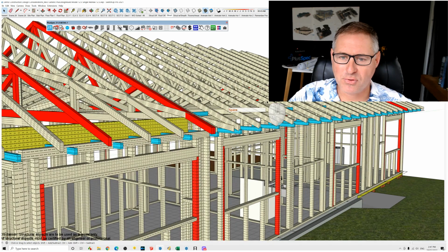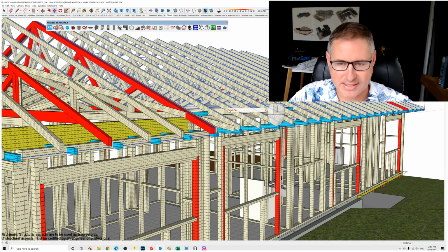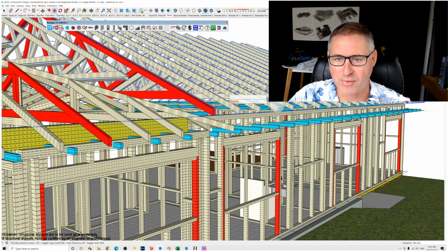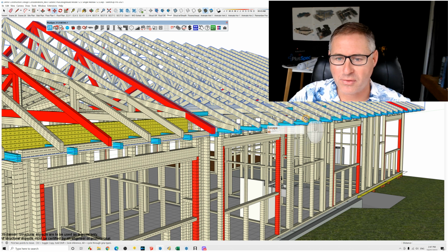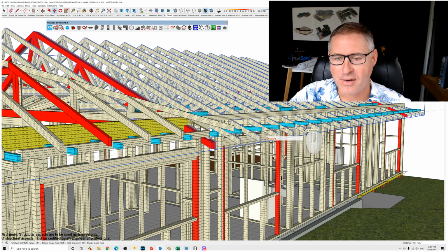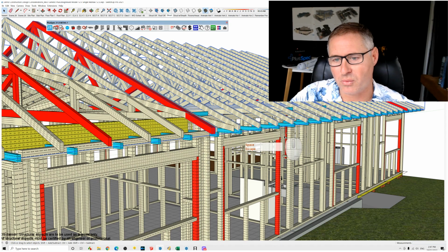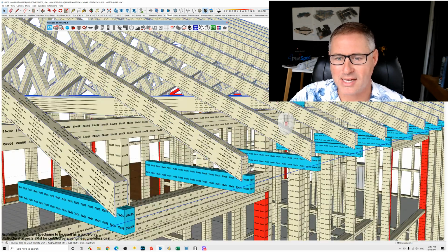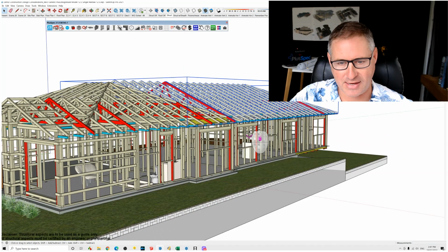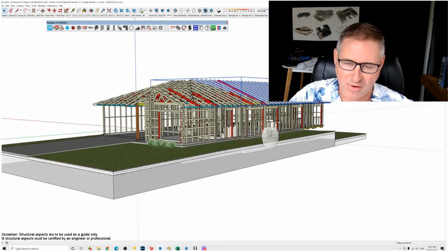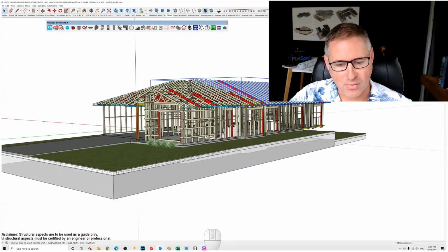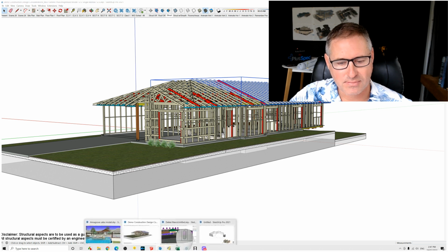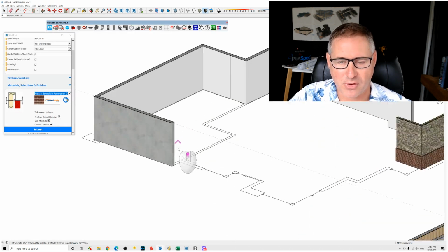So there's several things to take into account. Number one is the ability for the roof to lift off with wind, and also the weight on the roof that pushes down, right? So every time we design or we build, the critical point of the design is actually the structural point, or the intersection between the underside of the rafter and the underside of the ceiling joist, if there's a ceiling joist. Right, so if I go back to that other model that we had there, let's have a quick look and explain this a little bit further.